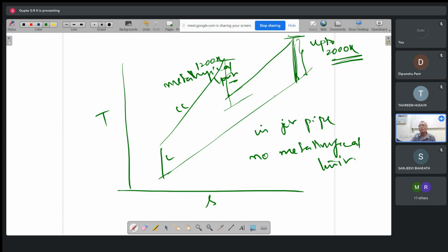So that is the advantage of afterburning. Whenever it needs some additional power, it injects some fuel in the jet pipe. So there will be additional thrust. And once that is over, I can stop the fuel supply into the jet pipe. Okay, that is the way I can have it.